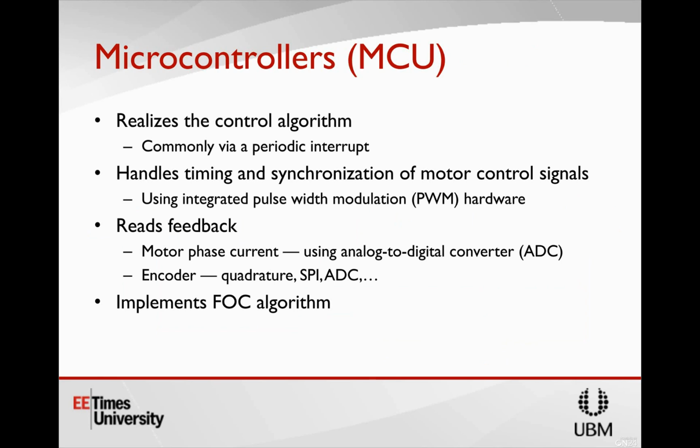So the microcontroller really is what implements this field-oriented control algorithm. It implements all this math in order to simplify the control of our motor and make it so we can control based on those DC values of IQ or torque and ID or flux. So the relative timing of things inside the microcontroller is very important. That's why using a periodic interrupt with field-oriented control is actually more important than it is with trapezoidal, because we need to time out when certain events happen, and they need to happen at a specific timing relative to each other.